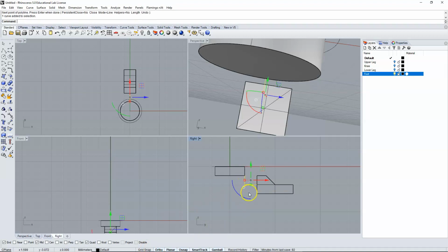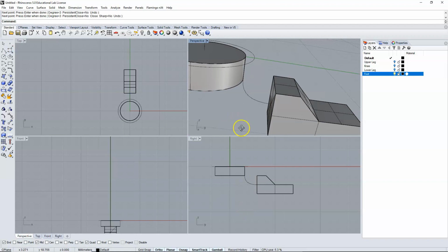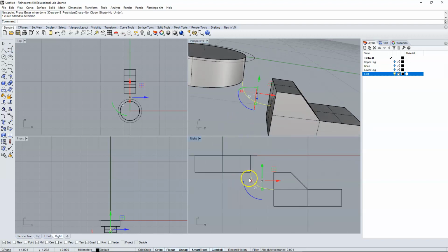and we will connect these. Again, that's a straight line. We wanted to do this with a curve, so I'll try one more time. There we go. There is our curve. One last thing, I'm going to turn on the control points and move that in 0.5. Negative 0.5. Negative 0.5 as well. And right click to remove those control points.